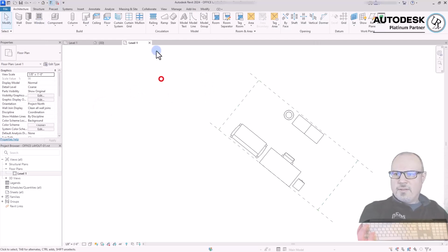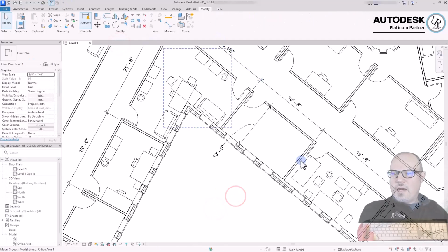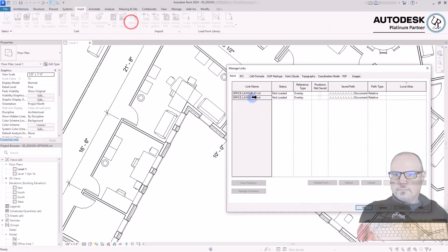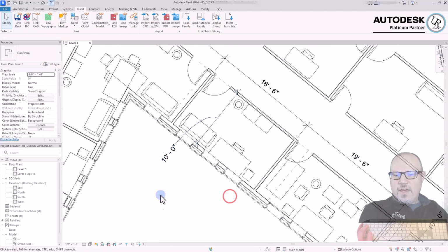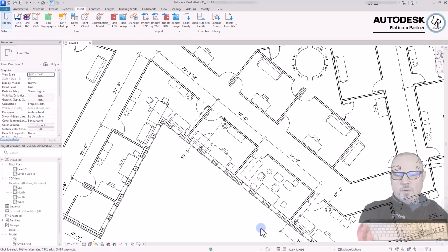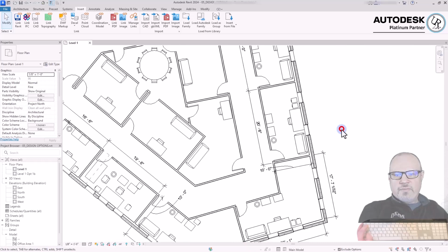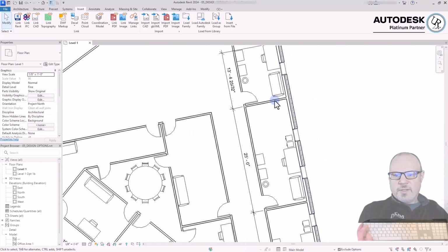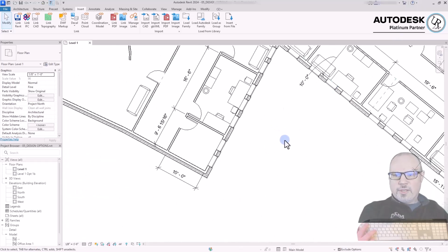And then when you save that file, go back into your project, and then load that linked file back into your model, it will include any changes that are made. That way, members of the team can be working off-site or remotely outside of the normal network environment that would be required if you're using Revit Collaboration, or if they're not using the BIM 360 environment collaborating in the same file, giving you a little more freedom.